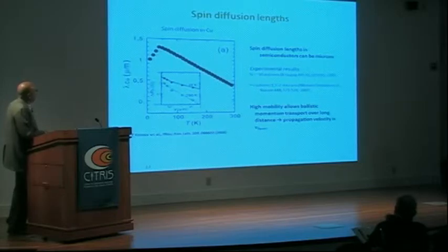operation of this interconnect could be ballistic, in other words, non-diffusive, over a distance that's not related to the spin diffusion length, but by the momentum transfer, the momentum mean free path, which in graphene, a very high mobility material, could be quite long, also on the order of a couple of microns. And so we could probably imagine a spin-based interconnect with at least an interconnect length in the neighborhood of 10 microns or so.